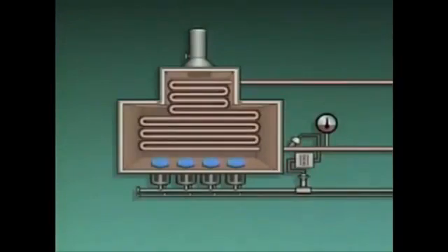A potentially dangerous airflow problem is insufficient airflow at the burners. If there's not enough air at the burners, some of the fuel sent to the furnace may not get burned. With unburned fuel in the furnace, you may notice that the firebox is hazy. Also, since the fuel is not burning completely, the outlet temperature of the process fluid could go down.